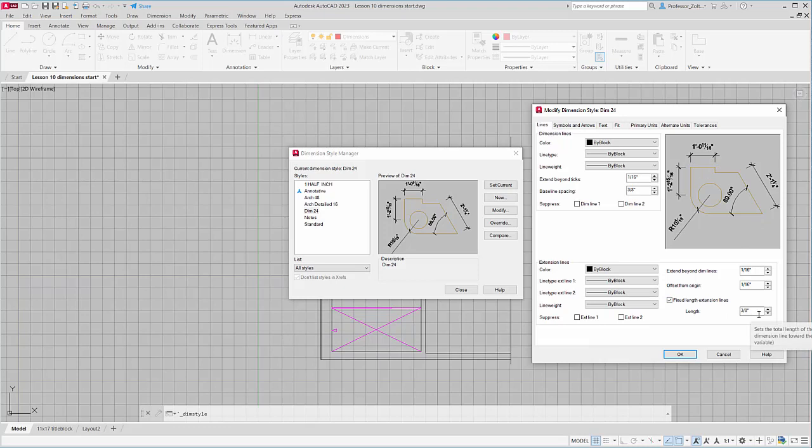The fixed length simply means that if I move this dimension line past 3/8 of an inch, the actual extension lines, this gap will follow me and it becomes larger. Now that's 3/8 of an inch on a printed page, on an actual layout page, not in the actual dimension of the image. And I'll try to clarify that later on.